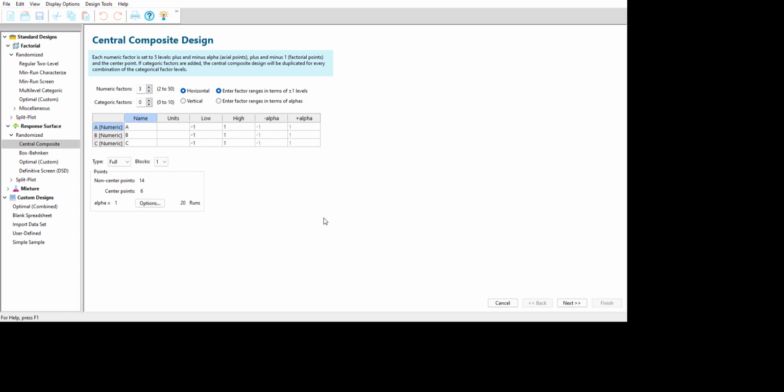So we will put the three parameters here. For example, if we are conducting a turning operation in mechanical engineering on a lathe, we will have three basic parameters, that are speed, feed and depth of cut. These are the three basic parameters. Here we will place their unit. For example, it is RPM, it is mm per revolution and depth of cut will be in mm.